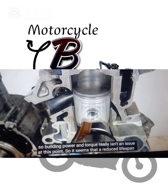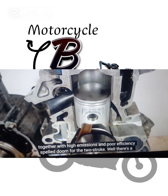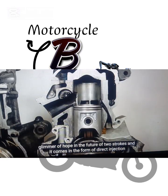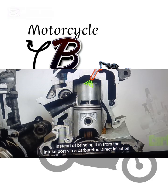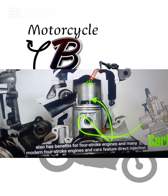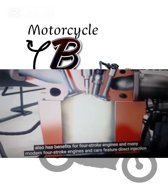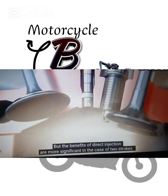So it seems that a reduced lifespan together with high emissions and poor efficiency spelled doom for the two-stroke. Well, there's a glimmer of hope in the future of two-strokes, and it comes in the form of direct injection. Direct injection basically means that we're spraying fuel directly into the combustion chamber via an injector, instead of bringing it in from the intake port via a carburetor. Direct injection also has benefits for four-stroke engines, and many modern four-stroke engines in cars feature direct injection. But the benefits of direct injection are more significant in the case of two-strokes.